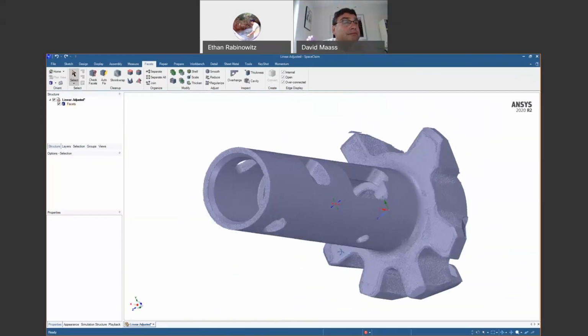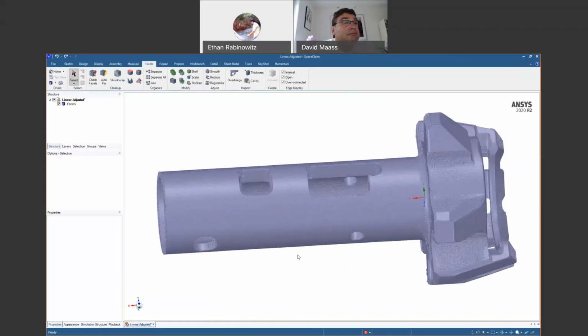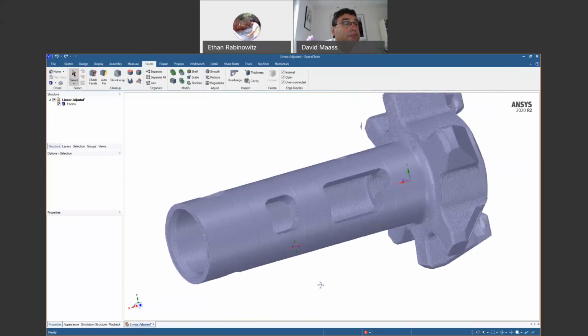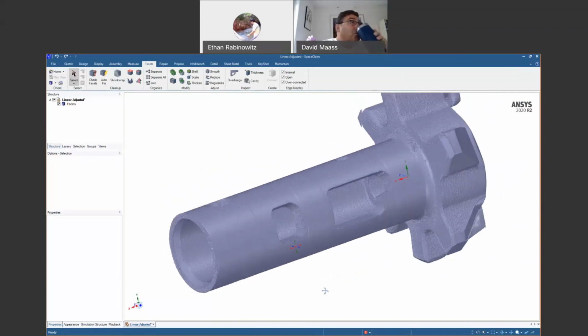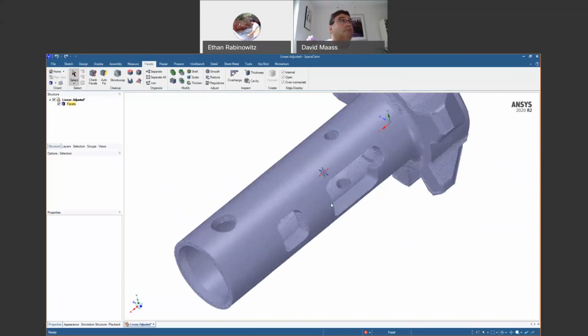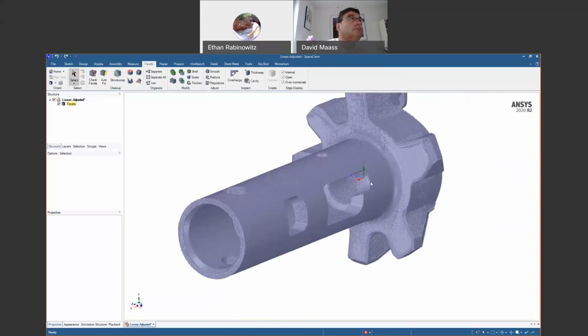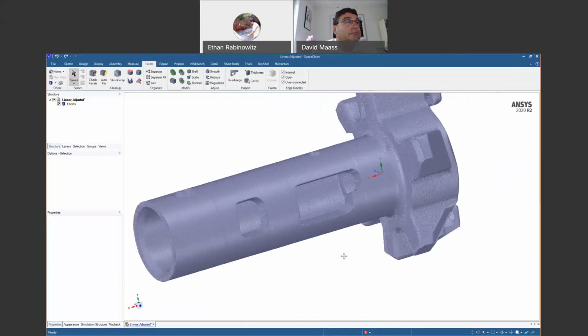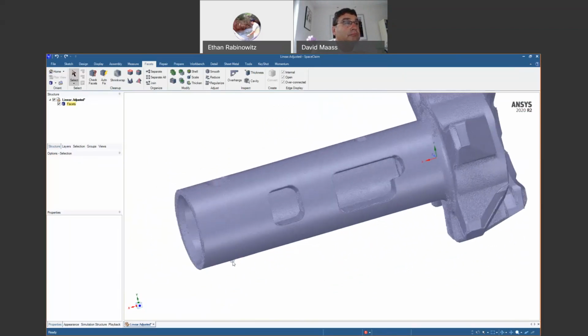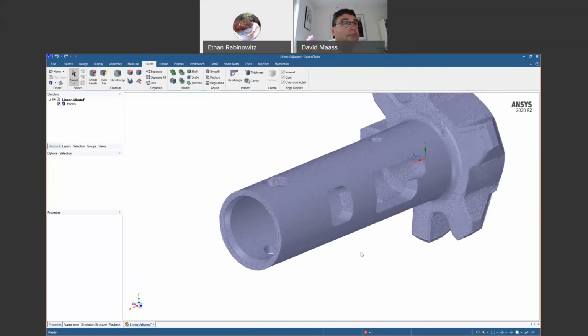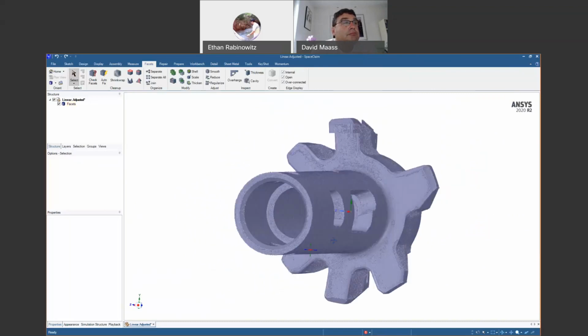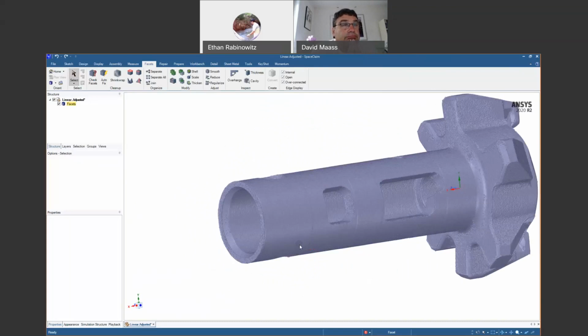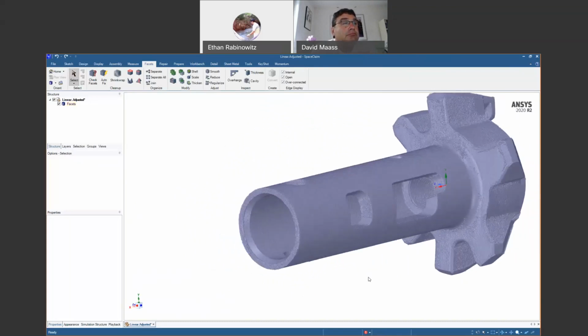Right, and in doing that, oftentimes whoever is going to be modeling this may have some knowledge based on how they expect it to be manufactured, used, etc., and that may drive it. Like if I'm expecting two pieces to clamp around this, then having it be cylindrical is probably preferred. If this was going to be inserted into something, it might be beneficial for it to have a little bit of a taper or a draft on it. Or, if this piece is going to be machined, cylindrical is really good. If it's going to be cast in a certain direction, you might need draft for the release from the mold. So sometimes, having some knowledge and understanding of what the model is going to be used for and how it's going to be made may draw different conclusions.